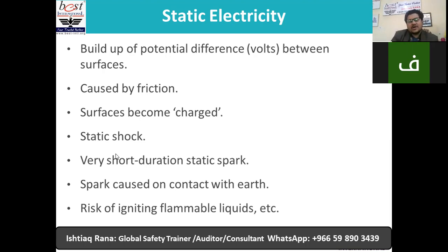Like you have an oil storage tank or chemical storage tanks. The first few liters you are going to put in the tank have a chance to produce static electricity because the liquid is directly hitting the ground.